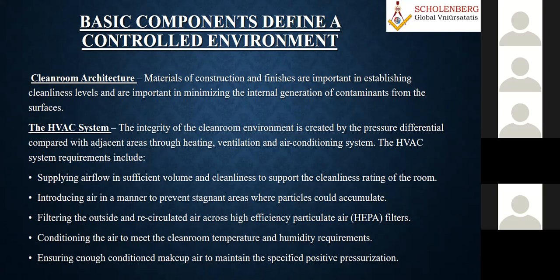So generally, you should ensure that the supply airflow is in sufficient volume and cleanliness to support the cleanliness rating of the room. So you have to properly refer to the standards, whether ASHRAE 170 or the ventilation standard, and as per that you calculate it. You should ensure that it is a sufficient flow as per the class level also.